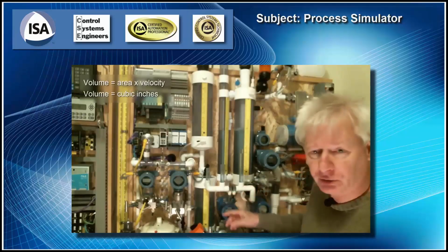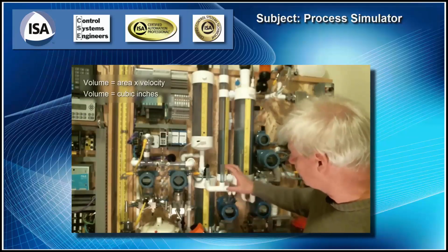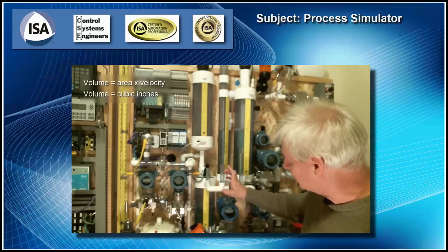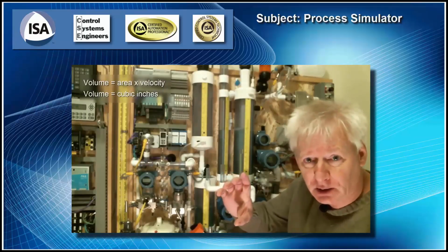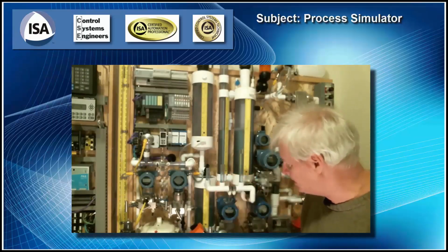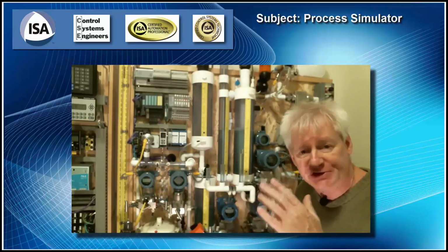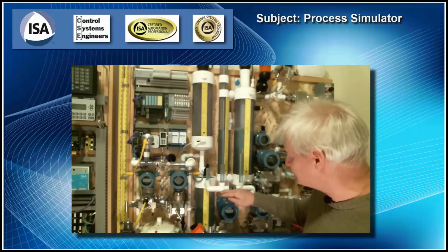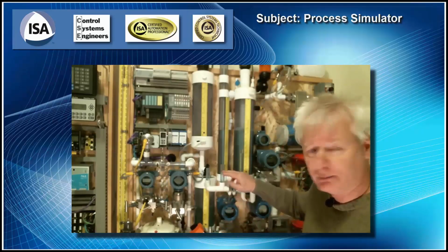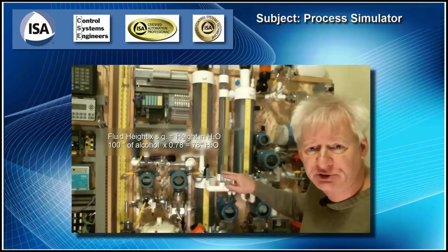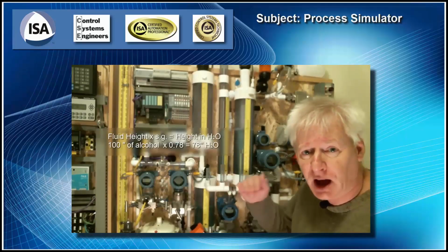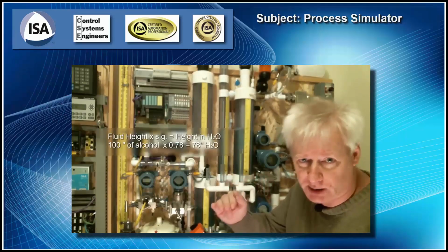And these are based on the weight of the fluid. Our weight of the fluid equals our density compared to the density of water. And this is a ratio. So it's either heavier than water or lighter than water, and this is based on weight. And this weight, as you saw, is proportional to the height of the column. So the height of the column times the specific gravity equals the height of if it was water.